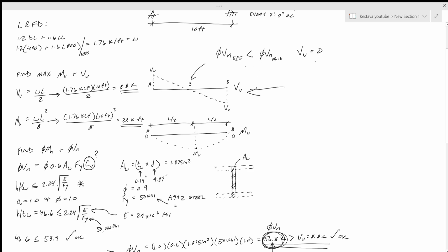And then you'd say, well, 3 inches each direction because the penetration is 6 inches wide. Even at that 3 inches, your Vu is still relatively 0. So no matter what you reduce your Vn effective to, you're comparing it to 0, which means that you will have enough capacity at that location.